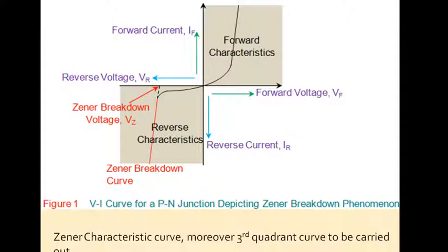Okay, similar curves are also shown here, so just check it up. The forward bias we are not doing as a characteristic study in this syllabus, so we are just focusing on the reverse bias. How to measure the reverse bias breakdown voltage? One has to draw a tangent from your data point and extend it to intersect the x-axis; that is your Zener breakdown voltage Vz. That way you have to get the exact Vz from your graphical representation.